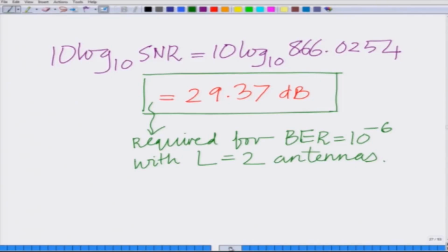Let us go back and see the SNR required to achieve the bit error rate 10 power minus 6.